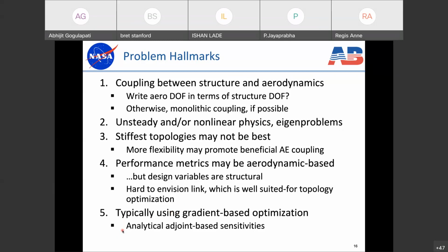And so an adjoint-based scheme means that we can compute the derivative of a small number of outputs with respect to a really large number of inputs, namely a really large number of design variables. We can compute those derivatives exactly with a computational cost that scales very weakly with the number of design variables. And so that's very powerful for, I would say, gradient-based optimization in particular, but topology optimization as well, because we have so many design variables that we have to deal with.